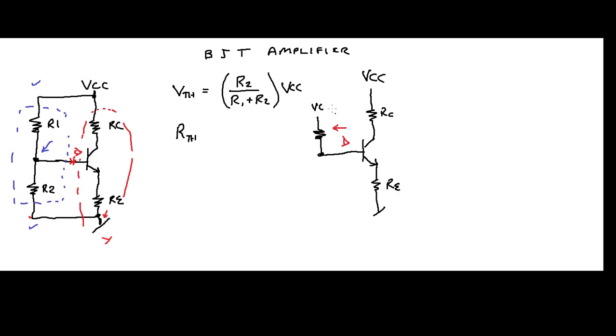Now, think about it here. That VCC, what did we say you have to do with our Thevenin? It's replaced by its internal resistance, isn't it? So if we come up, we're going through VCC, and we're going to assume it's 0. So that's just a wire. And the other part is just simply going to go, I drew that over, it's too far, I'm sorry, it's just going to go to ground, right?